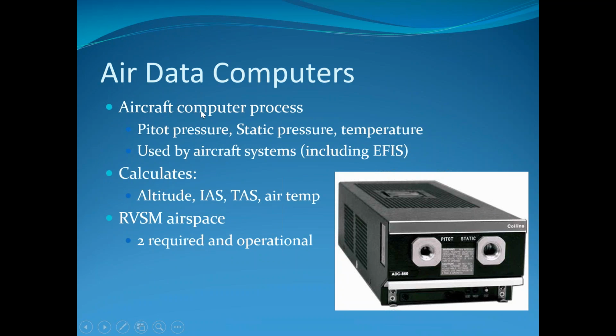And what those do is they process pitot-static pressures and temperature. They calculate your altitude, your indicated airspeed, your true airspeed, your air temperature. In order to fly into RVSM airspace, 2 are required and must be operational.